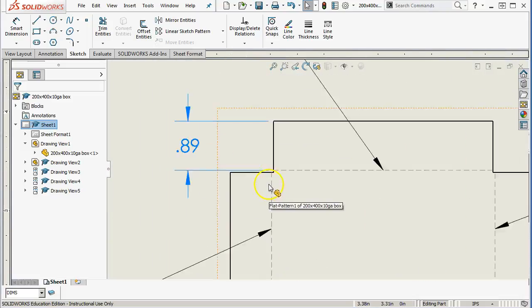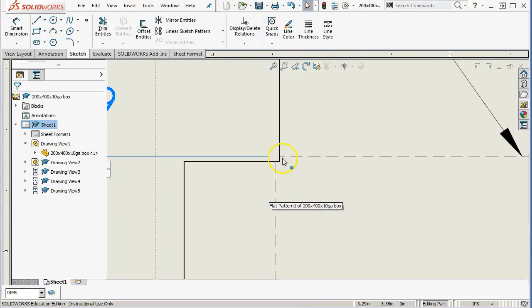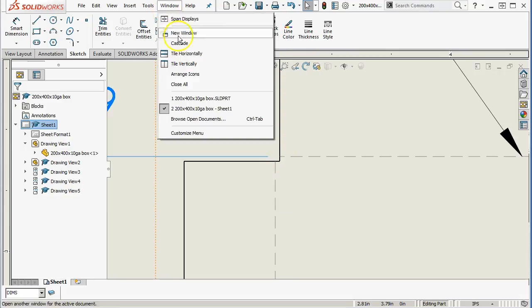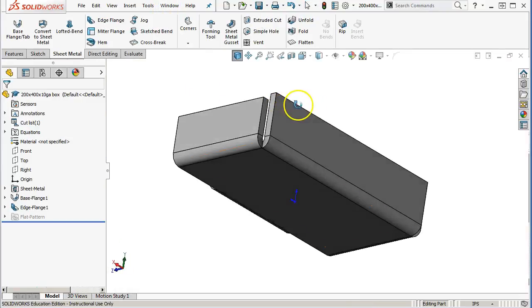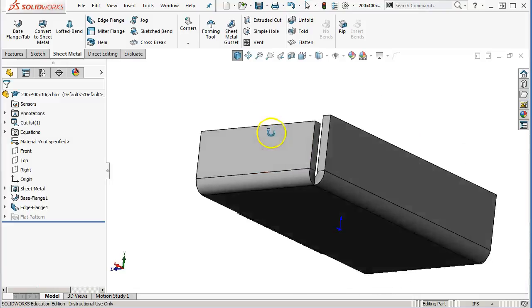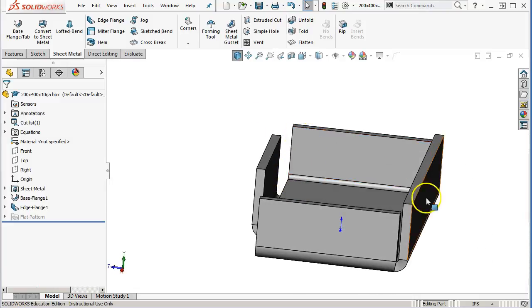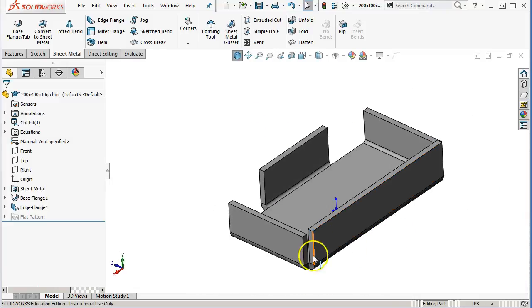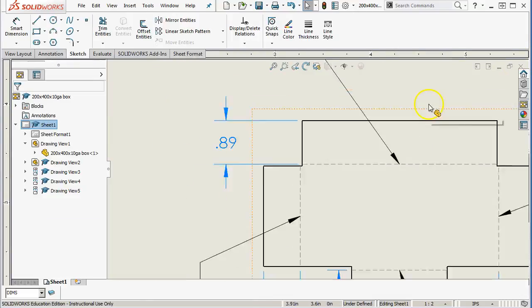All right, so to see where the bend is for that relief, for that corner relief, we come back over here and look at how it's calculated. As those get closer together, it will change the relief geometry in the corners, and then we can also change it for overlaps or for the gap. Okay. So that'll just be our first quickie example.